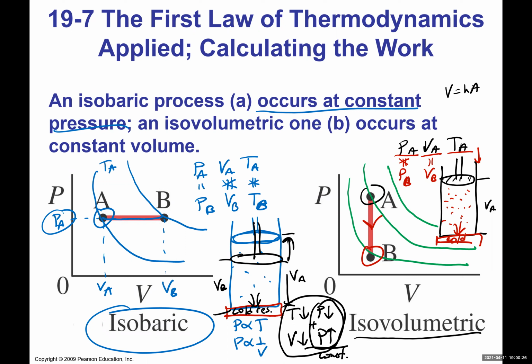Okay. That means in this case, I can assume that there is a Q, right? And what I have here is change in internal energy equals Q minus work done by the gas. But there is a change in energy, right? I'm removing, let's say, the heat energy. But the piston doesn't move. There is no expansion. The volume basically doesn't change, right? And if the volume doesn't change, that means there is no work done. That means in this case, this term is zero. That means my change in internal energy equals Q.